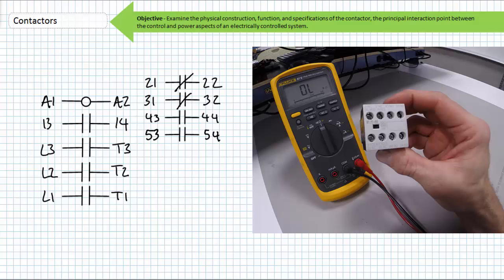This is the fifth set of auxiliary contacts associated with this contactor, so the first digit of these terminals is given the number 5. Since it is a normally open switch, it is assigned 3, 4 for the second digit, for terminal numbers of 5-3 to 5-4.